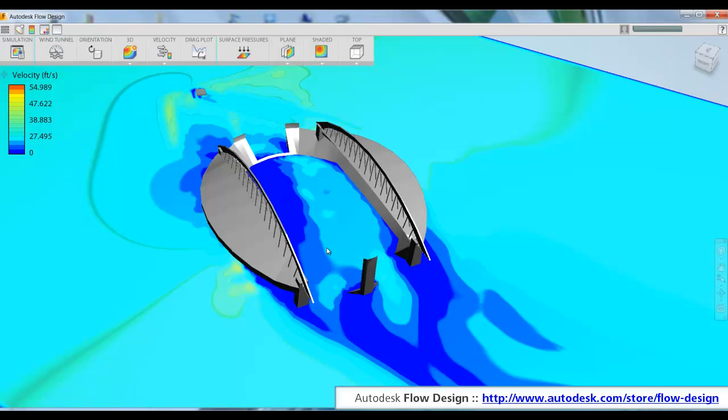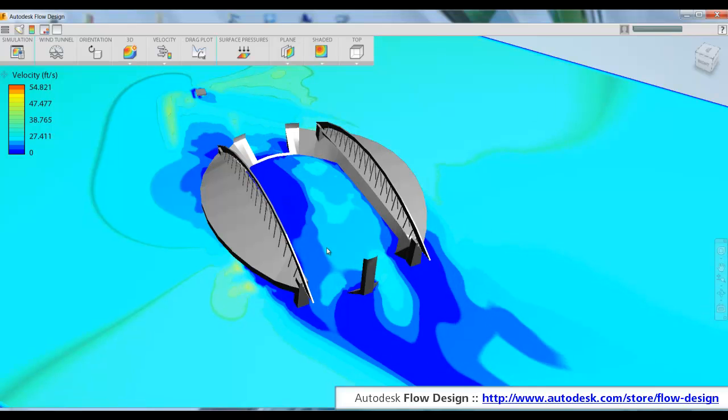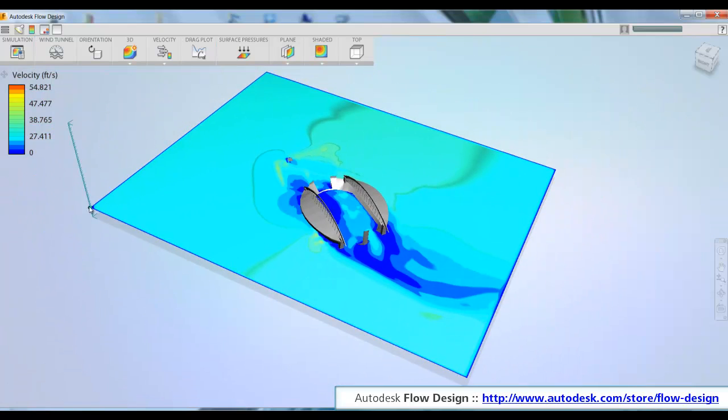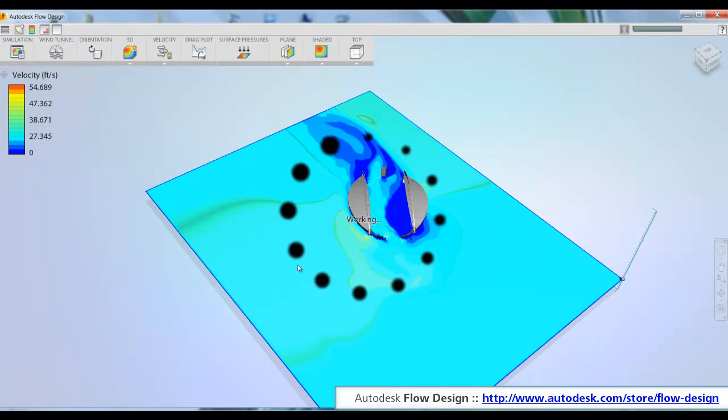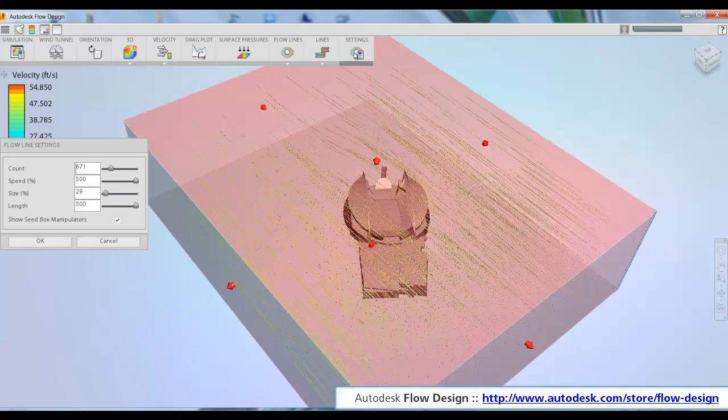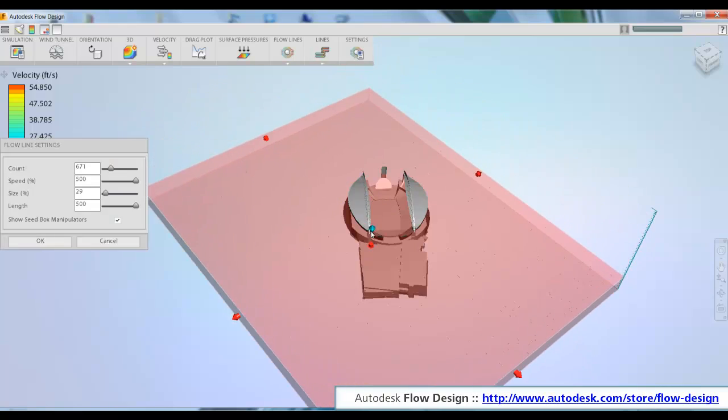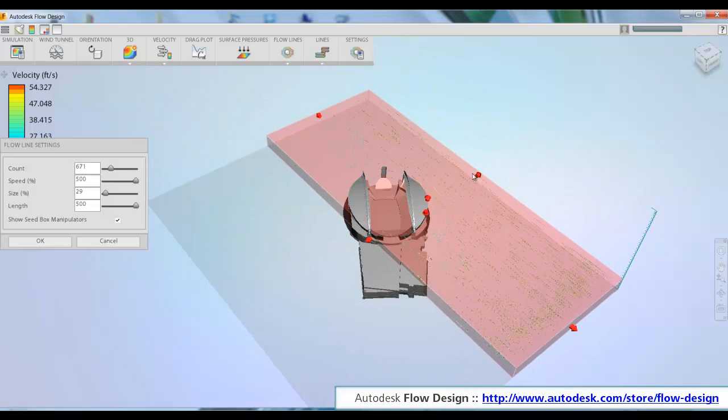So it looks like the result is starting to develop here, and again we do have a concentration of fast moving airflow on one side of the field. This time it's on the western side of the field. So despite the extra stands and the signboards on that side, which you might think would contribute to some extra blockage, it looks like we still have something to contend with when the wind is coming from that side.